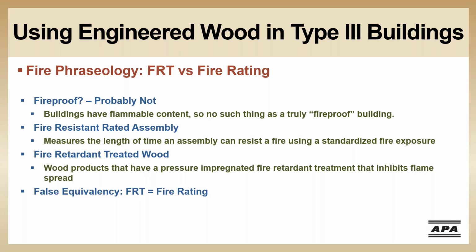So this takes us to the last point that I'd like to address, and that's products treated with a non-pressure impregnated process does not translate to being a fire retardant treated wood. Section 2303.2 of the IBC also requires that the ASTM E84 or UL 723 test shall be continued for a 20-minute period and not progress more than 10 feet.